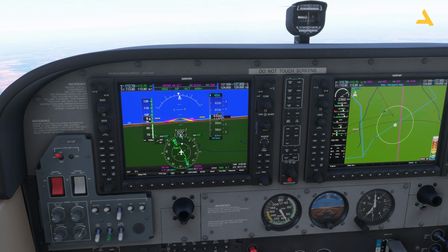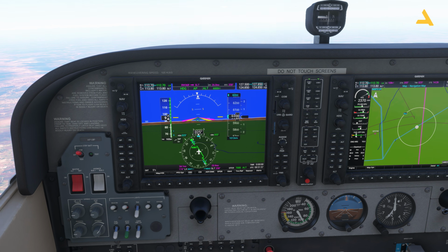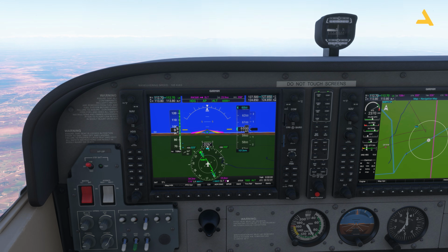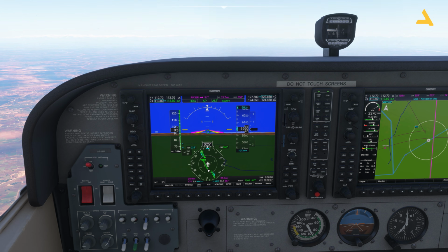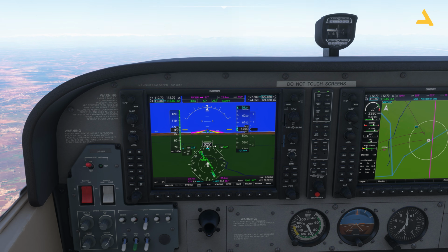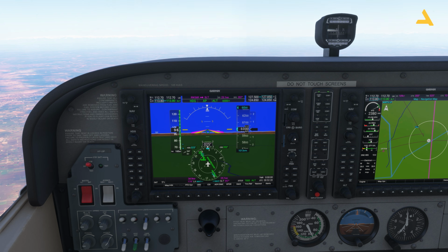So now this Lahore VOR is a bit far now, 34 nautical miles far, and this Sialkot is near. So instead of tracking Lahore, I will start to track Sialkot. It's better to track Sialkot because, and let's adjust the course. You can see the deviation was coming over here like this, because the course for Sialkot is 355 like this. So that's why, even if you move the course, that's fine, just set it to 355.